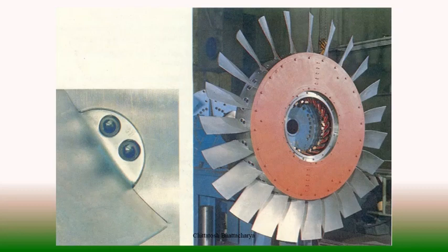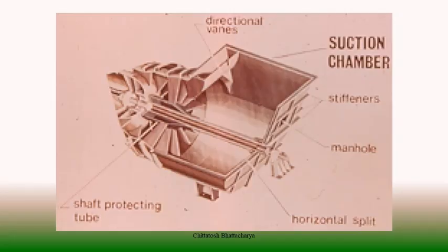Inlet guide vanes are also arranged similar to the blade pitch control type of arrangement. There is a turnbuckle arrangement. This turnbuckle arrangement is fitted with loading cylinders, pneumatic loading cylinders. From the remote position, these pneumatic loading cylinders can be operated, and with this operation, turnbuckles tilt the inlet guide vanes together in the same range.